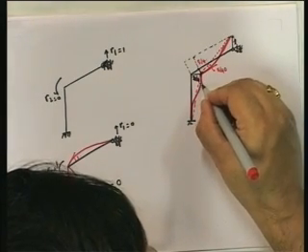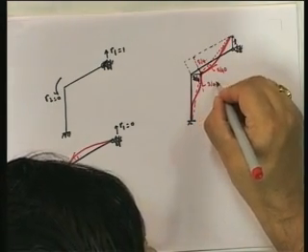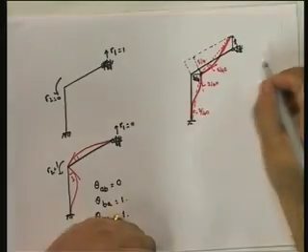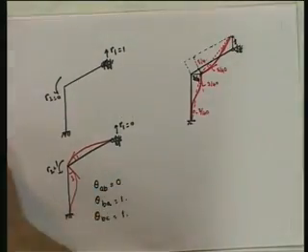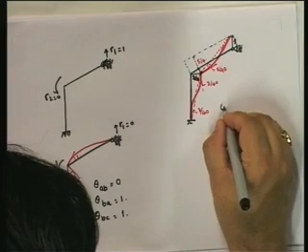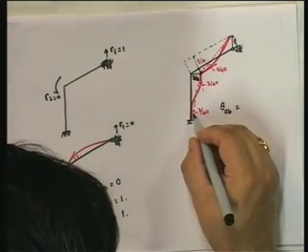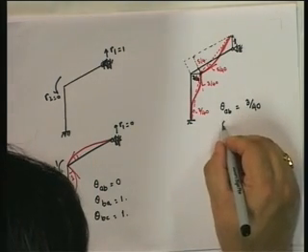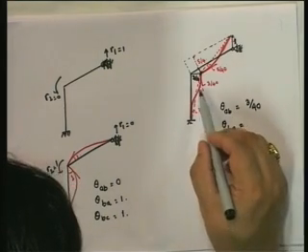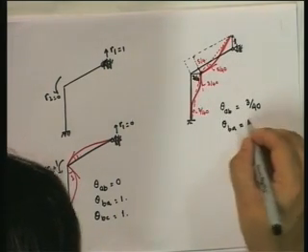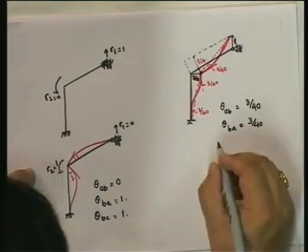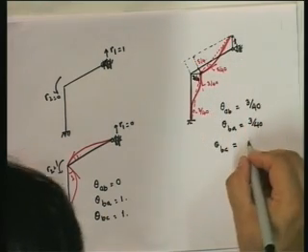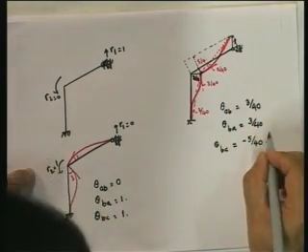This one, this angle is equal to 3 by 40. This angle is equal to 3 by 40, 3 by 4 divided by 10. So, these are our rotations, and therefore, if you look at it, theta AB is equal to, from the chord to the tangent anticlockwise, so it's plus 3/40. Theta BA is equal to, from the chord to the tangent anticlockwise, so positive 3 by 40, and theta BC is equal to, from the chord to the tangent is anticlockwise, so it's minus 5 by 40.